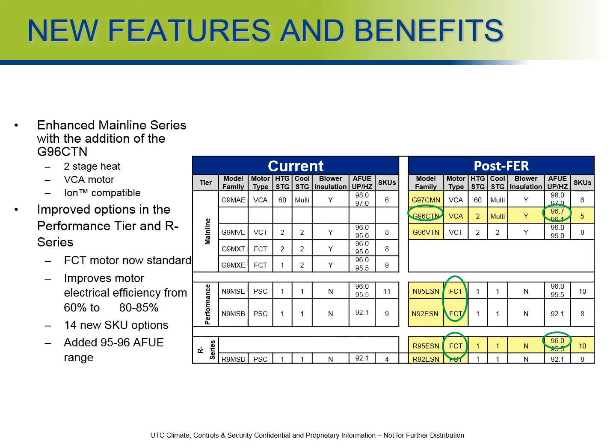But the three types of motors that we're going to talk about start with what we call the VCA, or variable constant airflow. That model blower is going to be a fully communicating motor. What that means is that the motor communicates its RPMs back to the control board of the furnace.